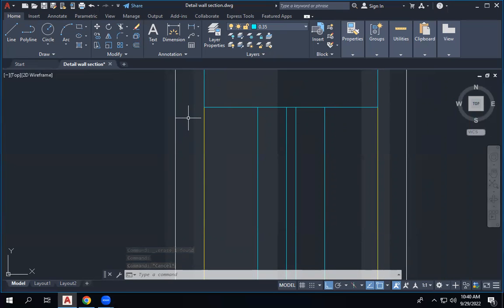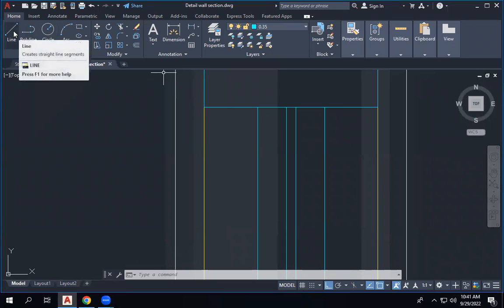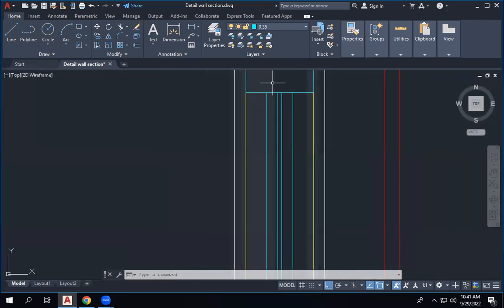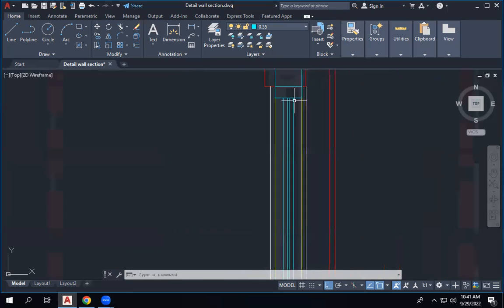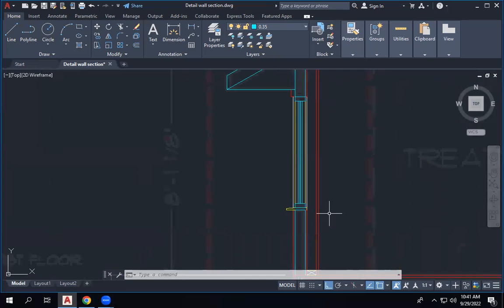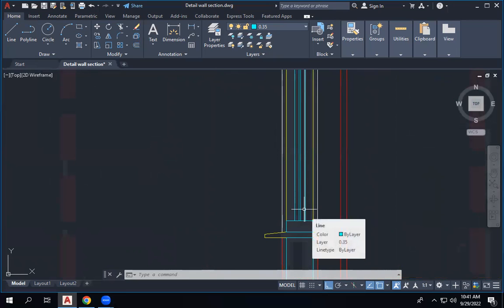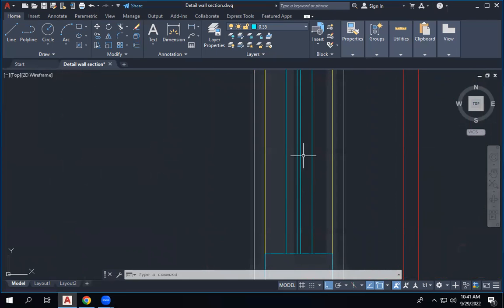I know aluminium extrusions will be in different sizes and all that. So what I did here is I did it in a standard way, because anyway we are saying that the doors and window details will be on another sheet. This is just to show that there's a window here. But remember, if it's a louvered or fixed panel or just openable or timber window, just draw that detail without putting the same thing for the louvers and the glasses. Don't do like that. If you put this detail for the louver window, it's a totally different thing. It doesn't need to be the exact size, but if it's a louvered window, you just draw the louvers like this.